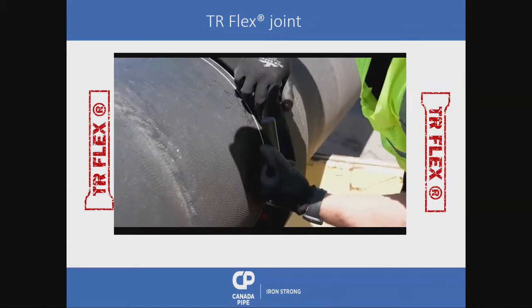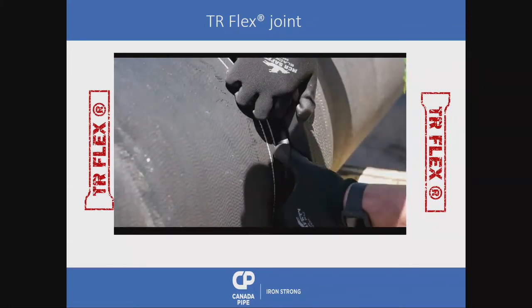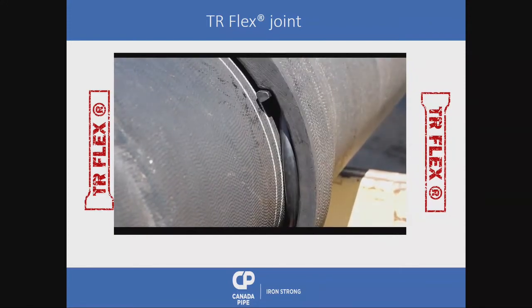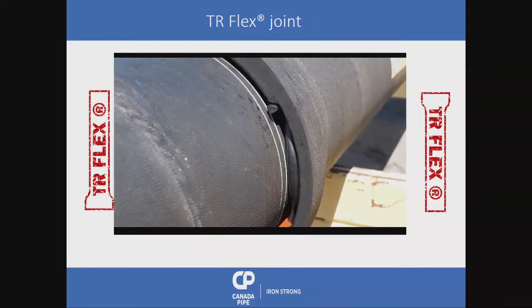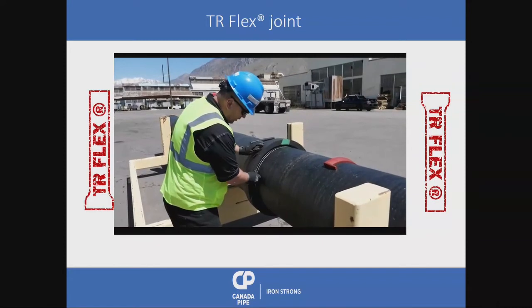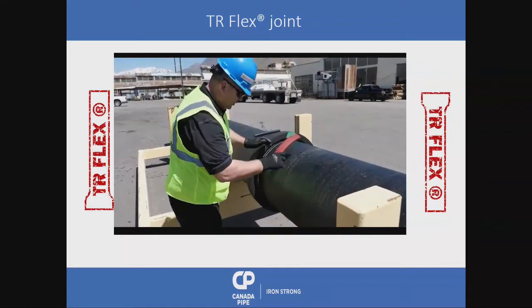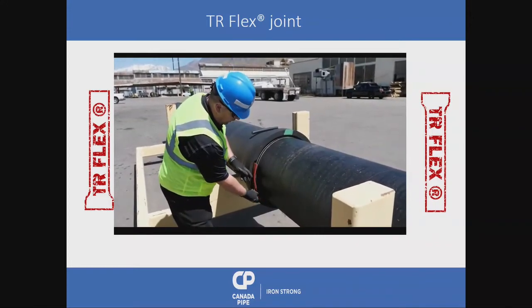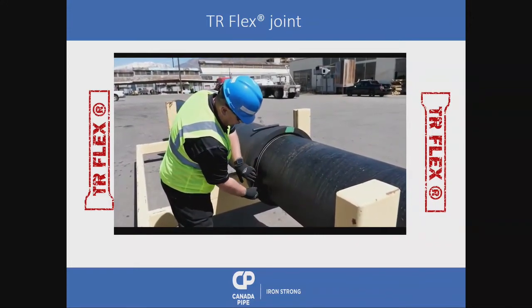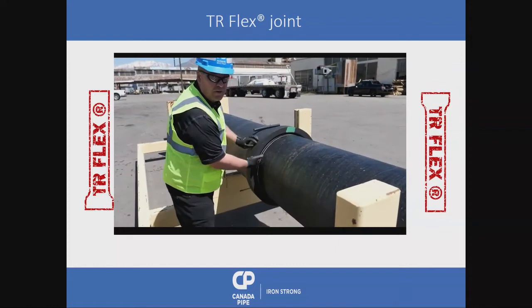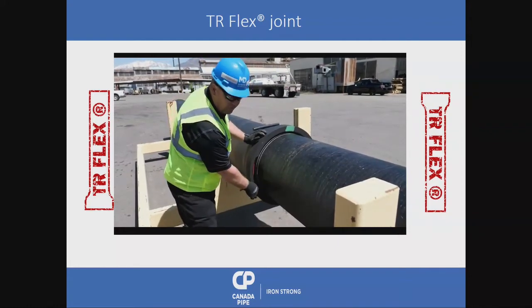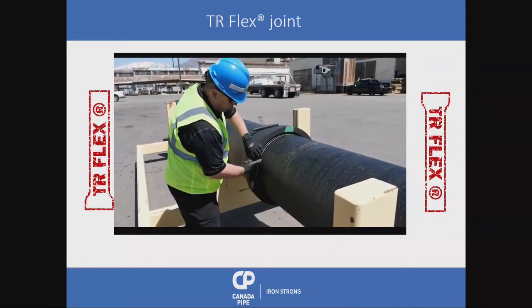Insert the rubber piece, the U-shaped form, to get the lock placed. First I go with the left hand lock into the slot, slide it down, insert my right hand lock, slide it up. Notice if I let go of that, gravity takes over and it falls down, so hold that back up in place,